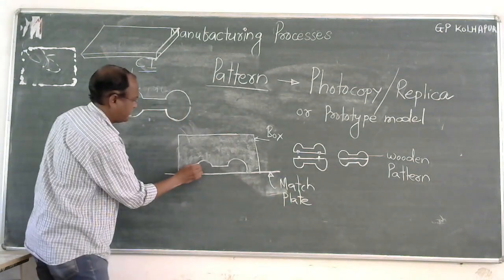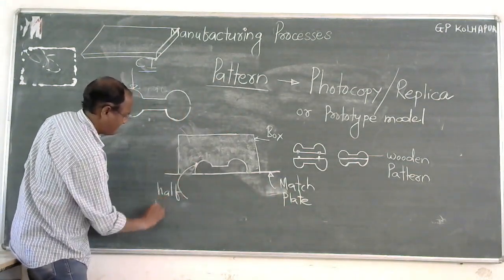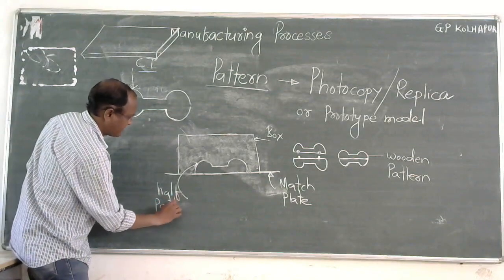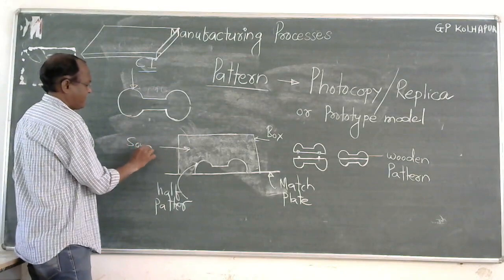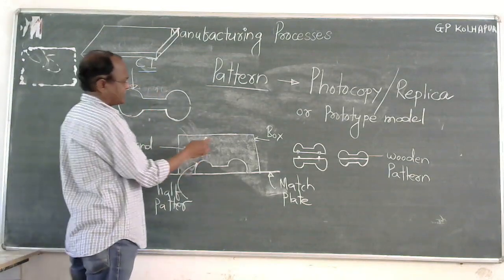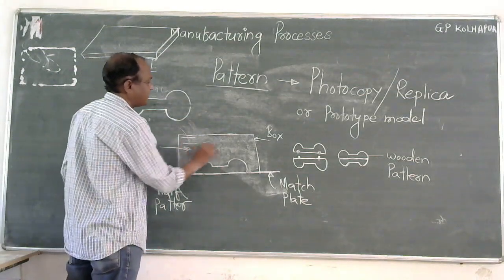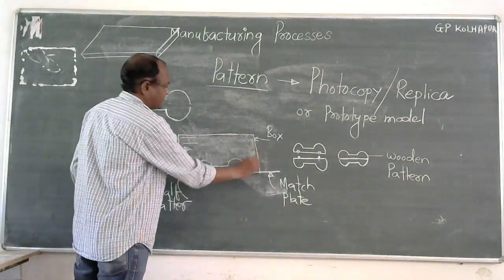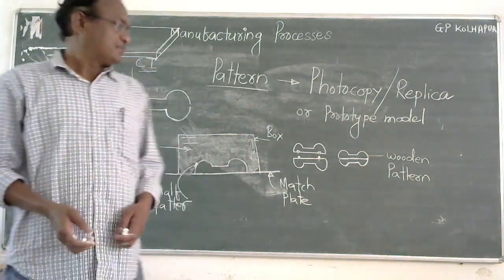And this is the pattern, the half wooden pattern. And this is sand. By means of some mallet or some tools, you press it, and that is called ramming of sand. Once you ram it, all the sand particles stick together.